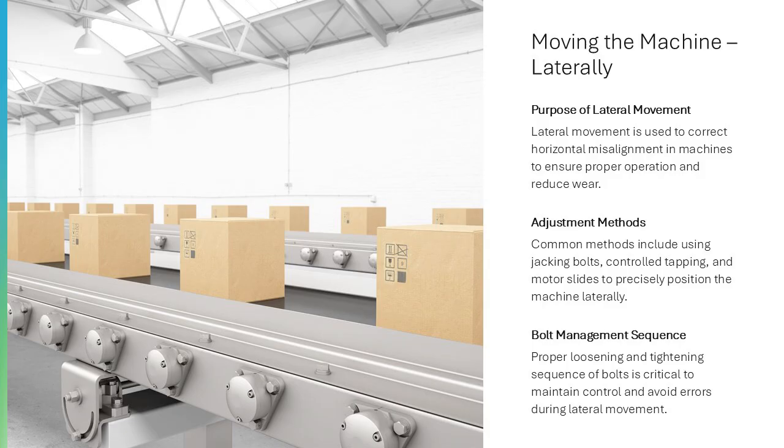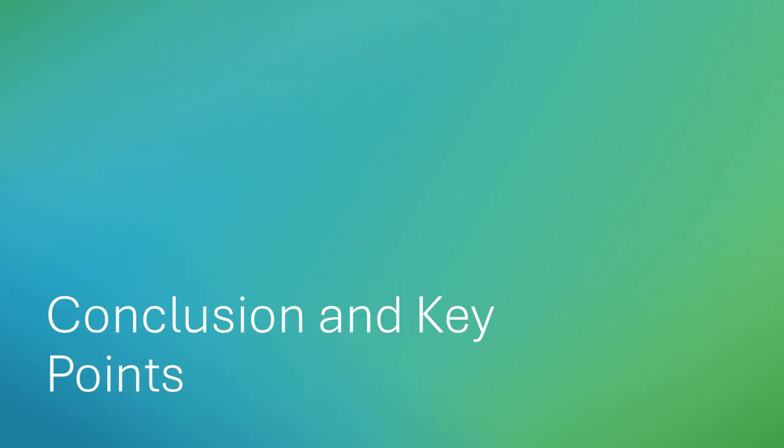Lateral movement corrects horizontal misalignment. This slide describes using jacking bolts, controlled tapping, or motor slides to adjust machine position. It also explains the importance of loosening and tightening bolts in the proper sequence to maintain control and prevent movement errors. Conclusion, key points, final slide.